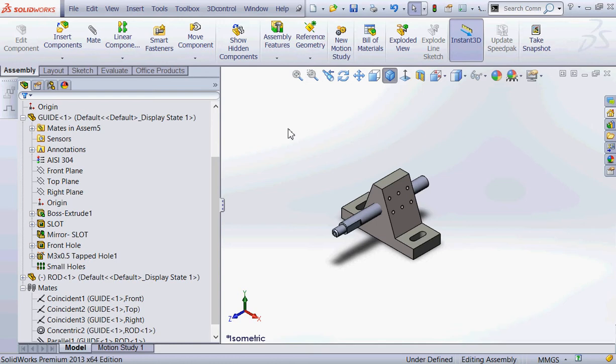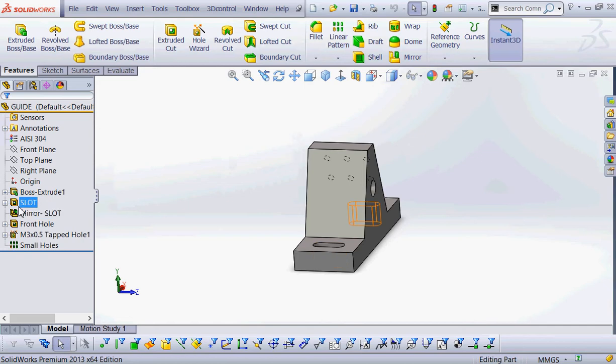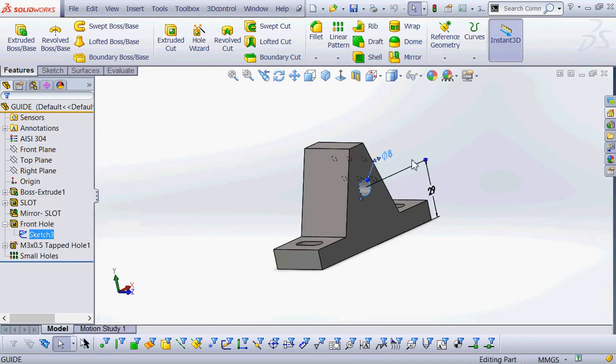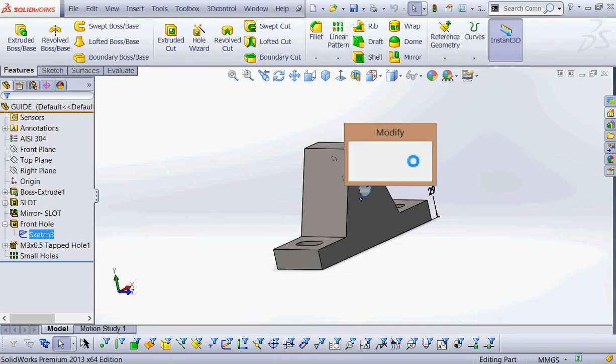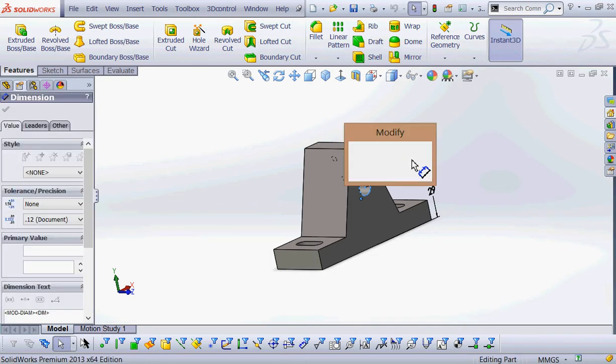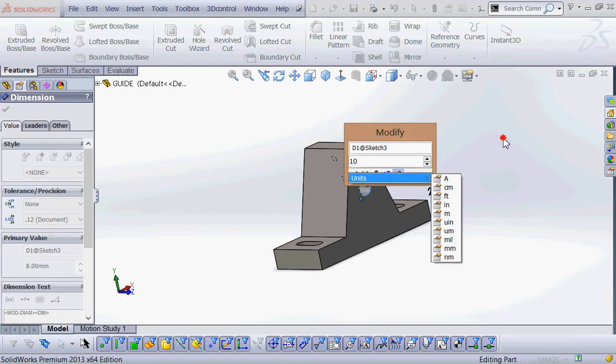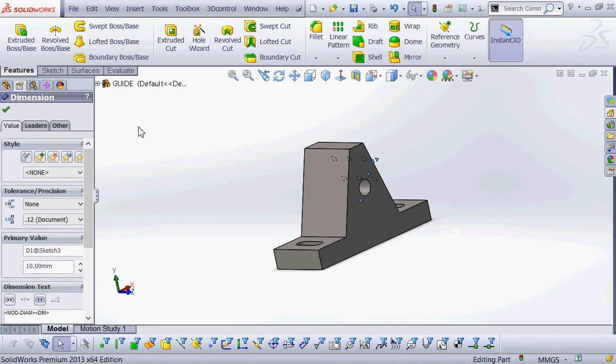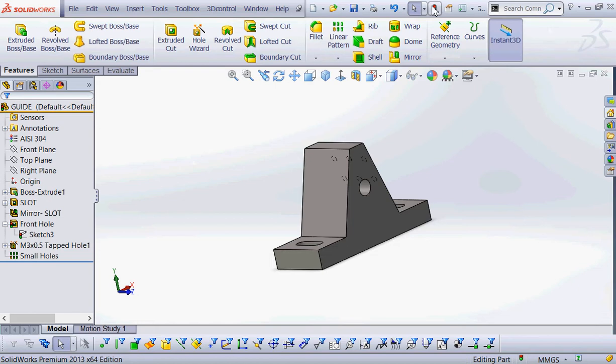Okay, so I want to use my keyhole. I want to say this flat face is parallel to this face. All right, so how do I do that? And if I say that that face is parallel to the other face, which degree of freedom am I eliminating? The degree of rotation? Yeah, I'm eliminating the degree of rotation, not the degree of translation. Translation meaning to move, rotation meaning to rotate.